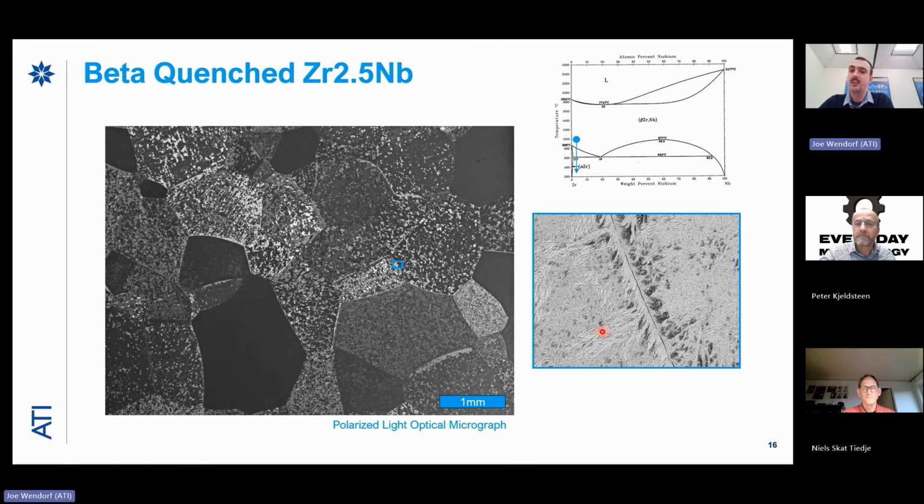And they're these really fine little laths that, when they're extruded into a pressure tube, help get to an optimal microstructure, which is a little bit more complicated. So I'm trying to keep it simple here. But I just wanted to share that BCC HCP Burgers pathway with you to explain how we get this really fine lath-like microstructure. Yeah, and this is supersaturated niobium.